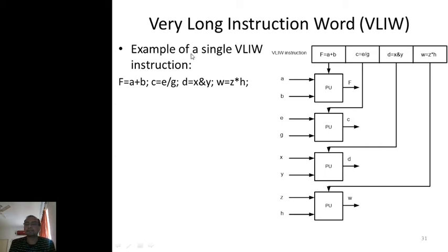Most modern DSP processors support VLIW, where the instruction word itself is very long, meaning it has multiple opcodes and multiple operands. Usually, if you refer to a microcontroller instruction, say add R0 R1, add is the opcode and R0 R1 are the operands. So usually an instruction has only one opcode and one or two operands. Usually operands are not greater than 2 in number, and the opcode is always 1. But in a VLIW DSP architecture, the opcodes are multiple: add, multiply, subtract, like 3 operations in one instruction, with operands such as R0 R1 add, R2 R3 multiply, R4 R5 divide, like that, right?